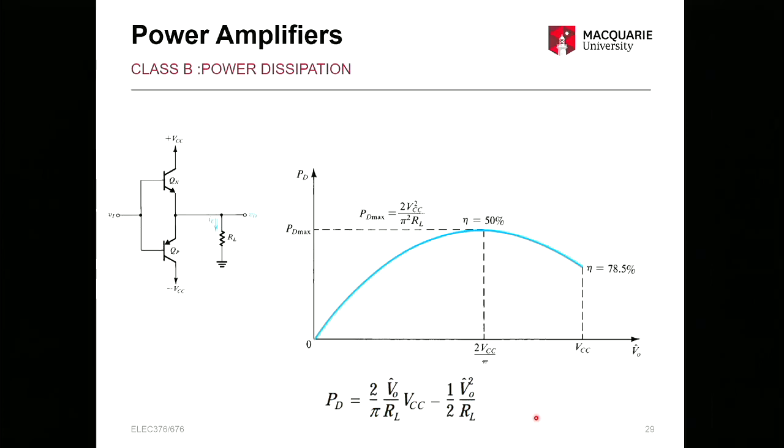So that's taken from, if we plot our equation for power dissipation, that's this equation here, plotted for every point for different V outs, okay? So that maximum power can be obtained by differentiating to get the point where the gradient of the curve is 0. That's the peak, yep? And that gives you your PD max. If you want to, you can go through all the maths of that separately. We're not going to focus on the maths here, but it's just differentiation to get that curve.